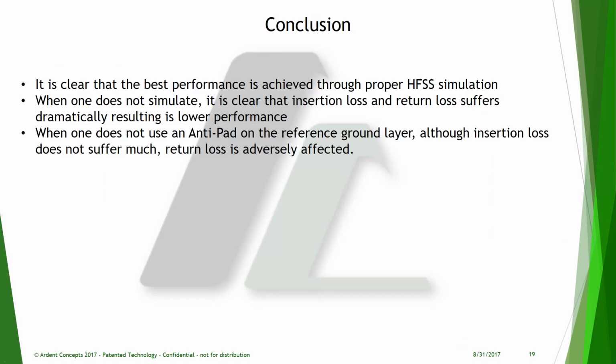So in conclusion, what we really wanted to drive home to you guys is that using the ANSYS HFSS or similar 3D field solving software, we want to simulate the realistic performance of our devices and our PCBs and our entire transmission line circuit. When one does not simulate, as was the case with experimental method number 1, it's clear that the insertion loss and return loss can suffer dramatically.